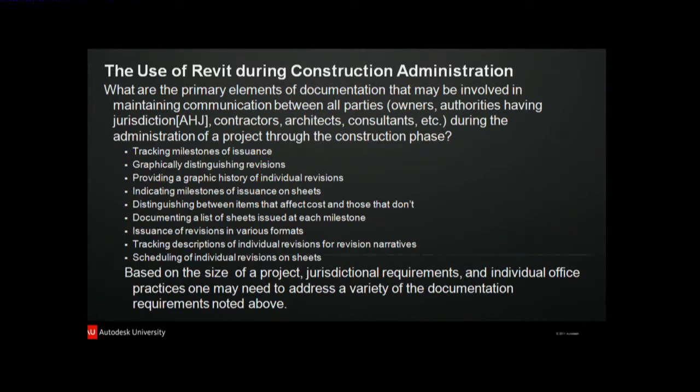An example would be a sheet index that maybe has a date that shows the current issue. Graphically distinguishing revisions, basically clouds, so you can tell what was revised. Providing a graphic history of individual revisions, that is usually revision tags.